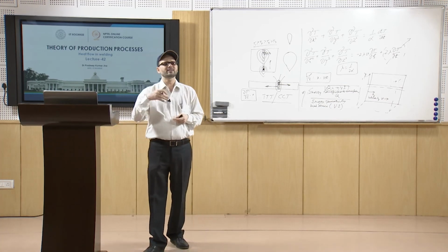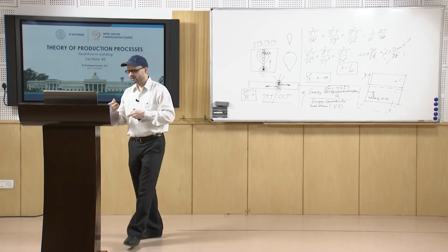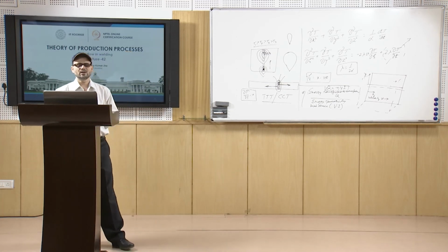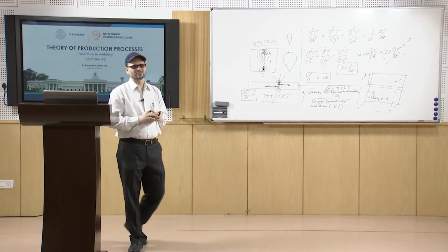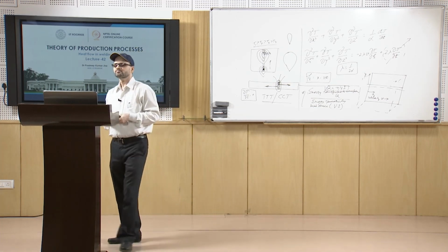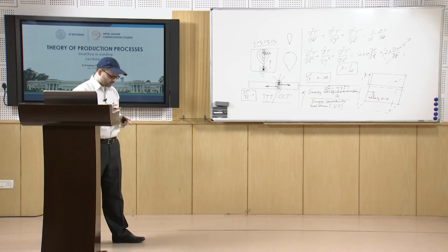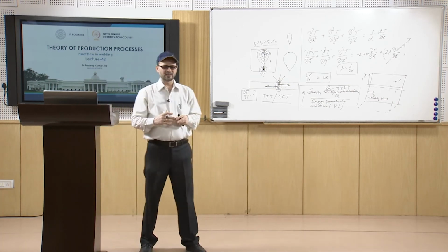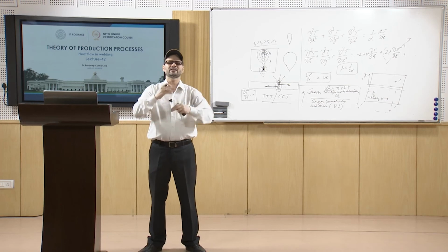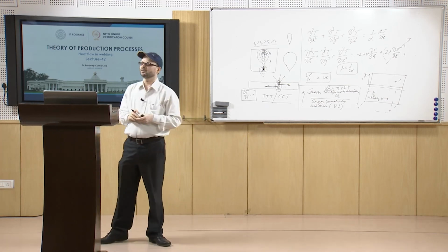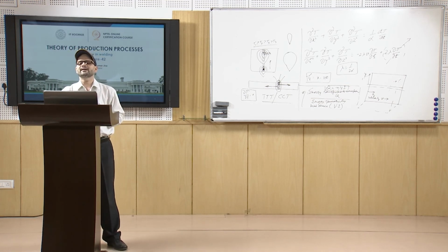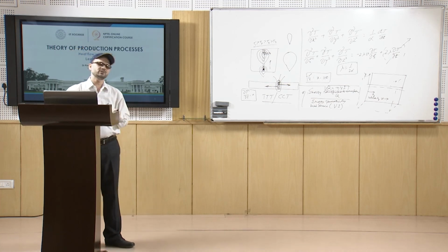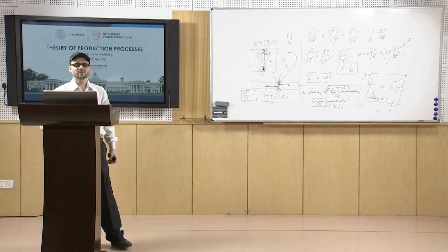It also depends upon the type of laser beam, the power density and so on. So, it can have a very small value of efficiency also. Then in oxyacetylene welding, you have other parameters like nozzle diameter, welding speed, material thickness and conductivity. These are the important parameters which decide the efficiency.